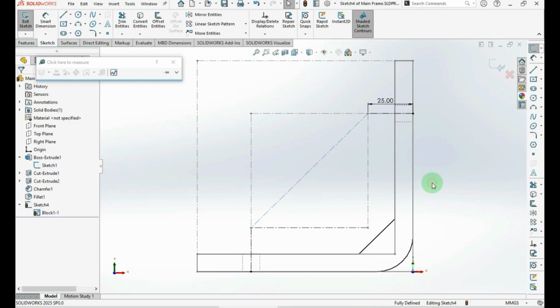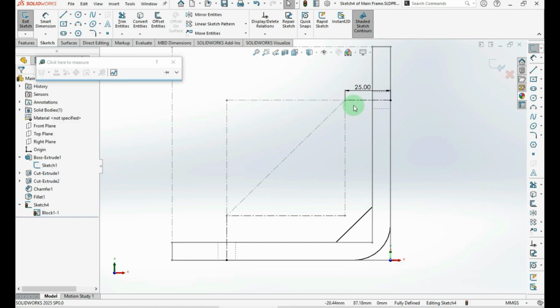Okay, I just created a block of sketch members. You see here we have a block. We can create so many blocks inside one sketch or move them around and use them as guides to transfer dimensions and entities from feature to feature, from component to component, and use those blocks as references to create other